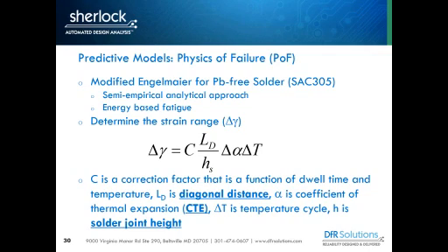I put something in the oven, I thermal cycle it, I get a time to failure. There's really not any physics that has been developed to the point, at least for solder, to make fatigue predictions based on actual material characteristics of the solder without having some type of test data to back it up.